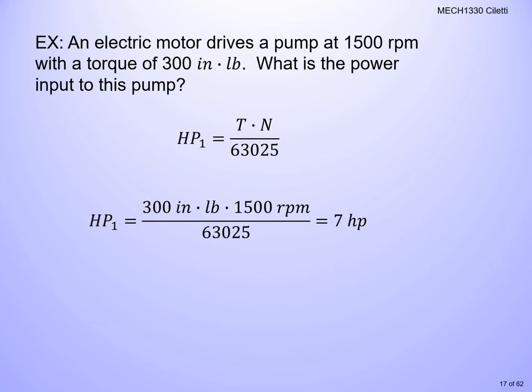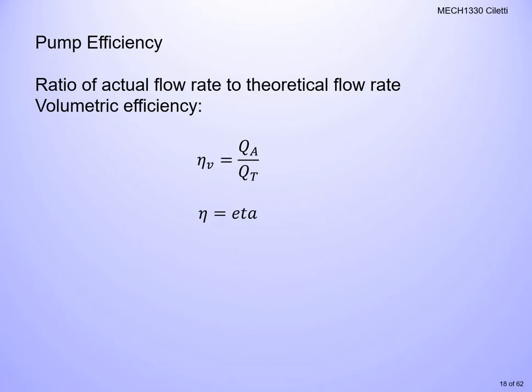Remember, we have an electric motor that's attached to the pump, and we generally have to have a certain pump speed. We have to have that torque that overcomes the load. So we need at least a 7 horsepower motor to run this. Most likely it's probably running off a 10 horsepower motor, but what it's drawing is 7 horsepower. You would do the same thing with metric.